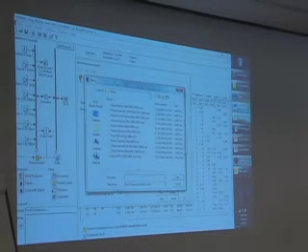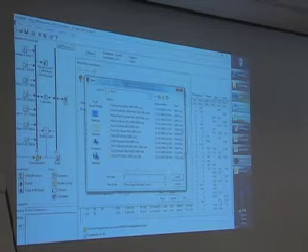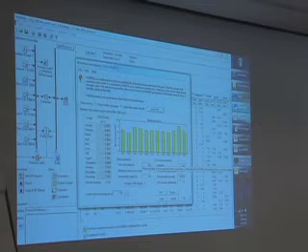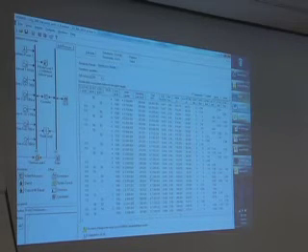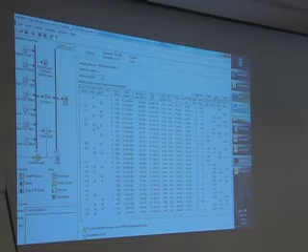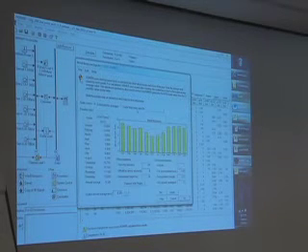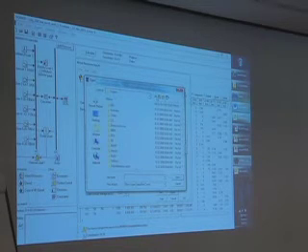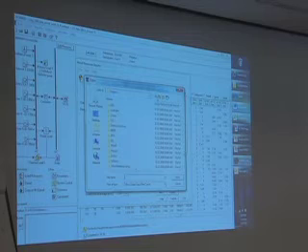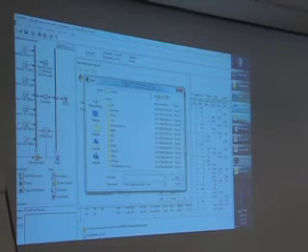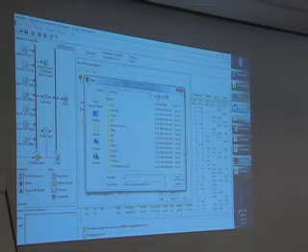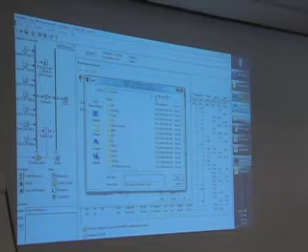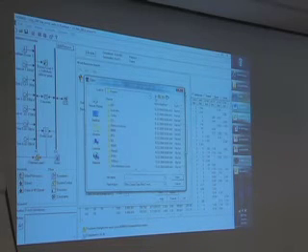Let me see if I can find a data set here. These are probably all hourly data sets, but let me just see. Yeah, so it said it was 60 minutes. I have somewhere a data set that's different than that. So do you import it as a doc file or as a text file? Text file. So it should be just a flat text file, but you should rename it, give it the extension WND for wind or DMD for demand. Give me a second to remember where the projects are.